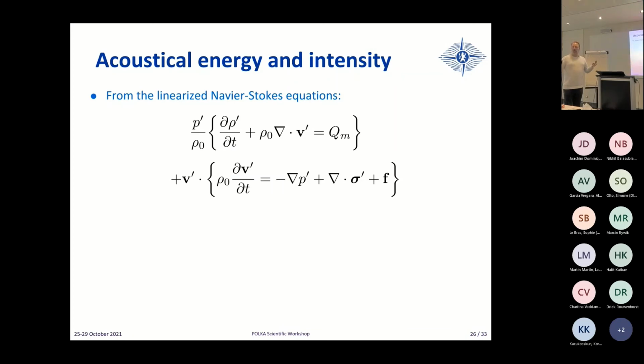If the balance of the acoustic energy radiated outwards of a system is positive, it means that acoustic energy is produced by this source. If the balance is negative, it means that acoustic energy is absorbed. It's also very convenient to establish whether a system is going to resonate or not. So this acoustic energy equation is very convenient for this, and it will lead to the Rayleigh criterion that you will possibly have seen already, which is a criterion for